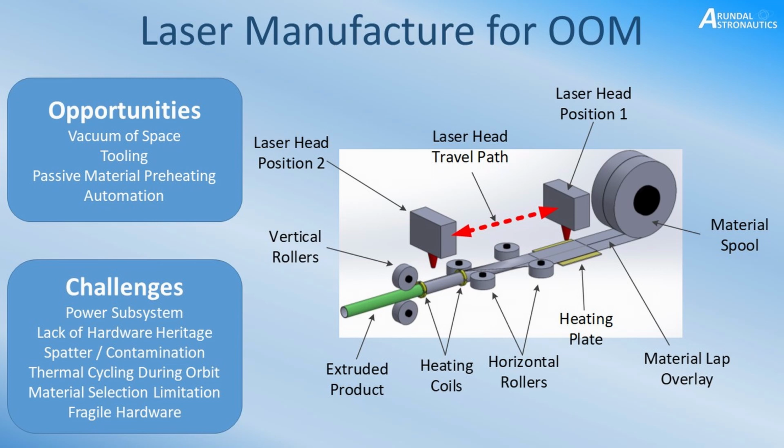From a laser system standpoint, this thermal cycling is also a problem, because if you try to carry out a manufacturing operation on very cold material, you would require more energy to raise the material to its melting point and vaporization, and if the laser isn't able to adapt to that power, for example, or it's not been designed for it, then you won't be able to achieve your manufacture, your laser weld or cut. So timing of these processes would need to be considered as part of the mission design.